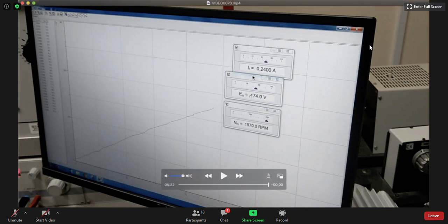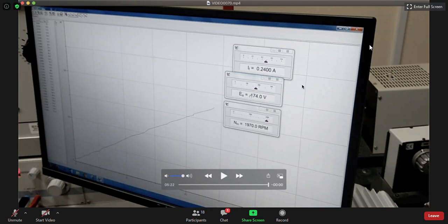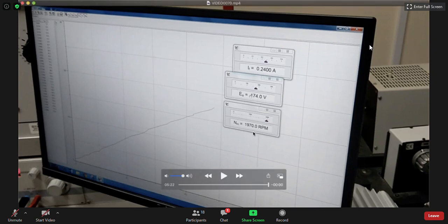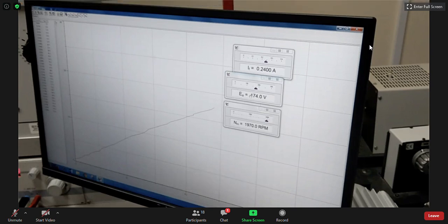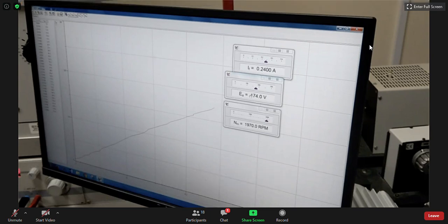Phi is coming because of this field current. I discussed with you that once the field current is flowing in the circuit, a flux is present. It means that the field current represents the flux. It means EA equals K into phi into omega. This N is RPM, but we have discussed omega. This is the same thing, just expressed here in RPM, but normally omega is expressed in radians per second. It means that this is speed. So we are verifying today the generation of the generator voltage.